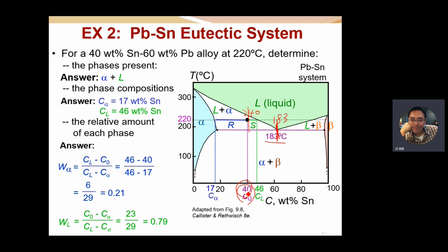If we don't choose this eutectic composition, say we choose 40% tin as the casting alloy, what's going to happen? We have to heat up to a higher temperature, and when we pour this liquid into the mold and it cools to this two-phase region, say at this point, its viscosity changes. Its viscosity gets higher and higher, so it's not easy to flow through the pattern of the mold you design.